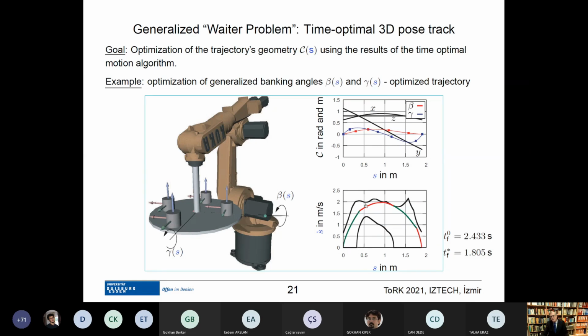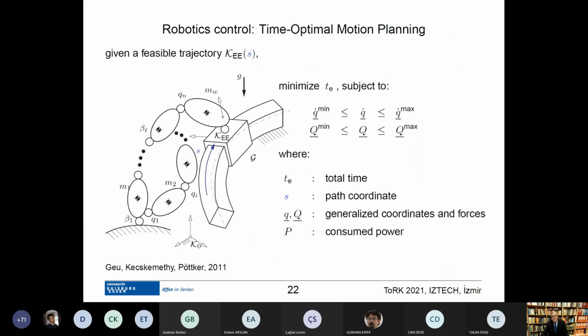But as you can see, these sequences are again non-linear, and more or less the task of the optimizer is to find the highest sequence of green and red curves so that they just touch the limit. Because if you don't touch the limit, then you still have a little bit more room to get faster. But if you are too fast, maybe this can happen here, but much later, then this trajectory doesn't work.